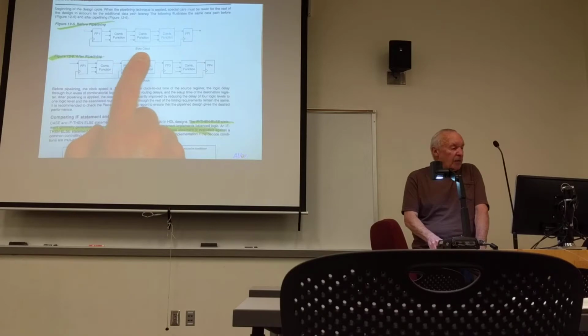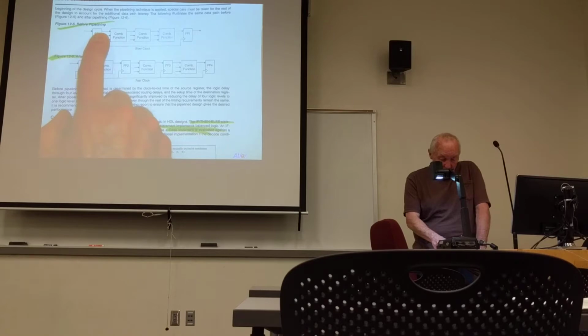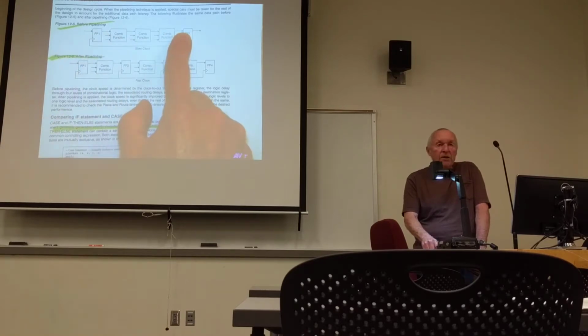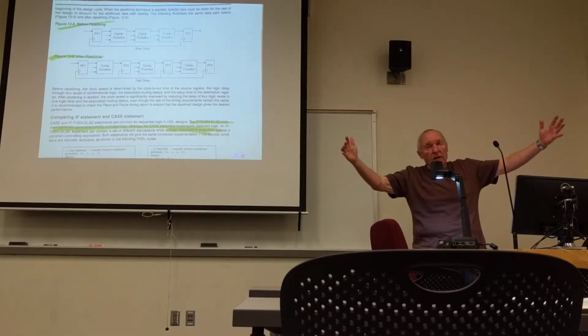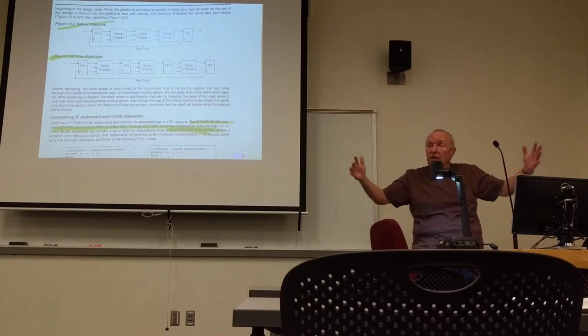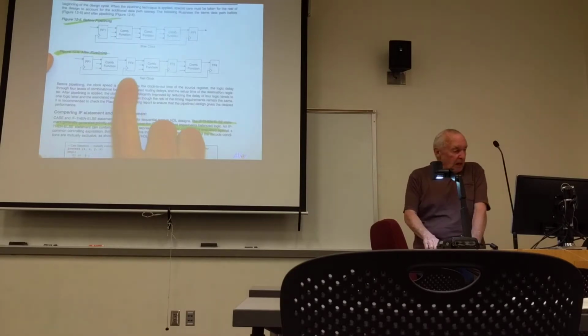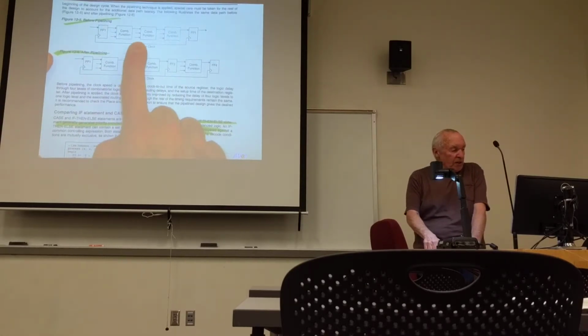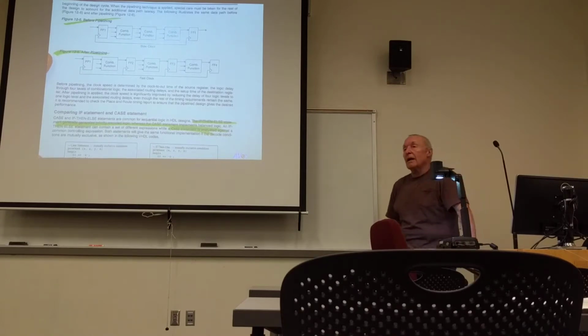And that means that you're going to have a clock with a relatively long period so that the output here, until you satisfy the setup time period here, the period is adjusted so that 2 successive, let's say, leading clock edges are far enough apart in time so that you don't run into timing problems. If you insert registers in between these combinational logic blocks, it turns out that you can have a much faster clock. So if you're having trouble meeting a timing constraint, what you may have to do is pipeline your design.